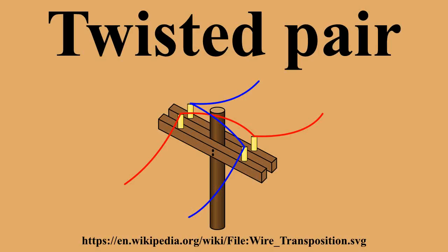Imbalance: differences between the two wires in a pair can cause coupling between the common mode and the differential mode. Differential to common mode conversion produces common mode currents that can cause external interference and can produce common mode signals in other pairs. Common mode to differential mode conversion can produce differential mode signals from common mode interference from other pairs or external sources.